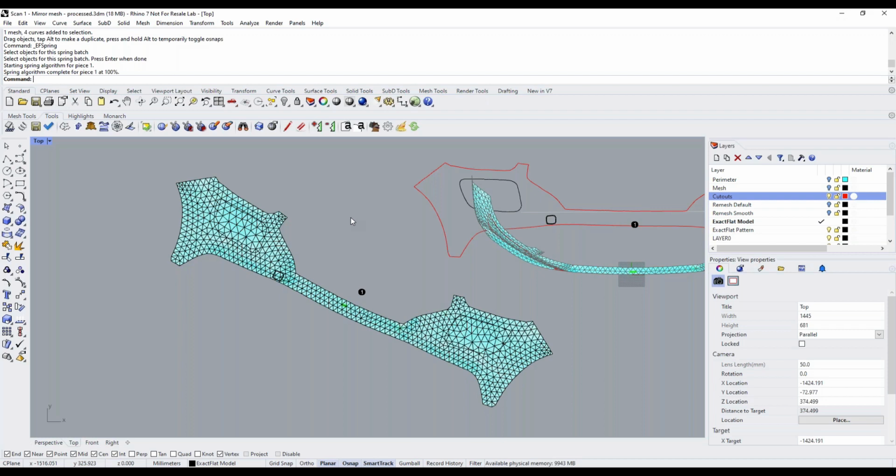Well, it depends on the type of edits that you're talking about, Chris. So first of all, we can produce a DXF output, and a DXF output is a layered file made for cutting tables or plotters, or we can produce a PDF. Both outputs are available to you. You can then either plot your output files on paper and then cut them out with a paper template, or if you have a cutter or you're going to send it out to a cutting service, you can send the DXF itself out to be cut on an automated cutting table. Either option is available to you.